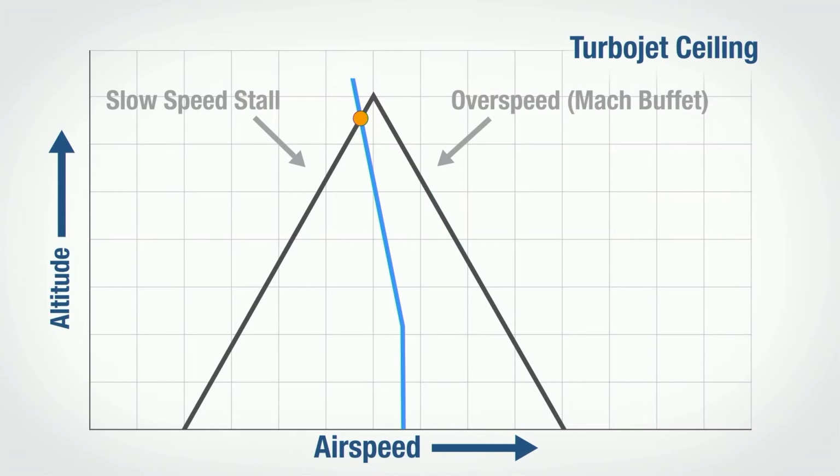But now if you look at a modern airplane, they're pretty much what we call thrust limited. Okay, so as opposed to this green line, we end up with the blue line. So first of all, you notice that the aircraft's power is essentially flat here until we reach a certain altitude. That's because most aircraft's engines now are derated or flat rated. And when we say derated or flat rated, essentially the jet's capable of producing a lot more power, but the FADEC system limits the amount of power that the jet can produce.